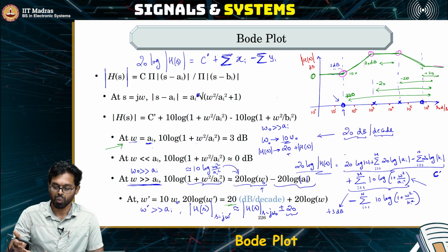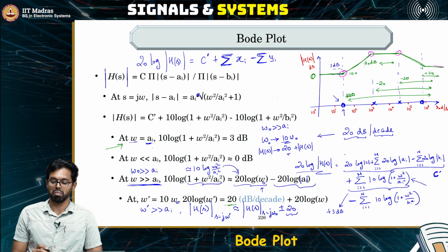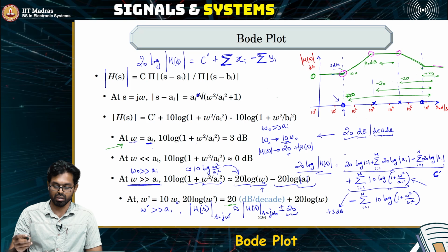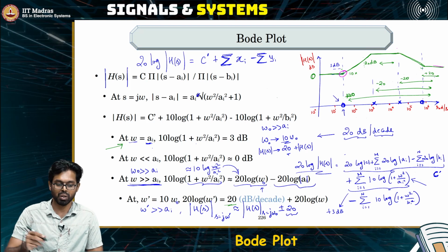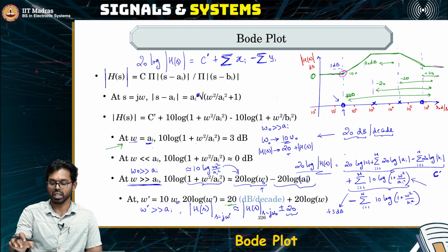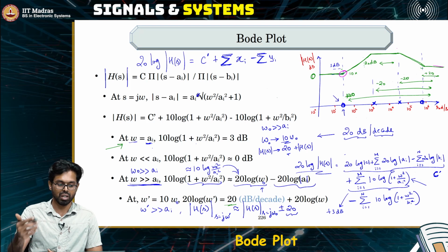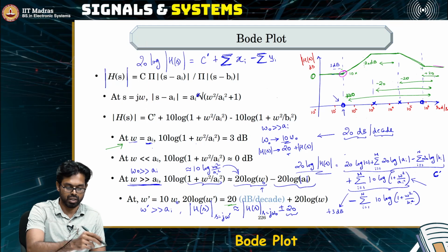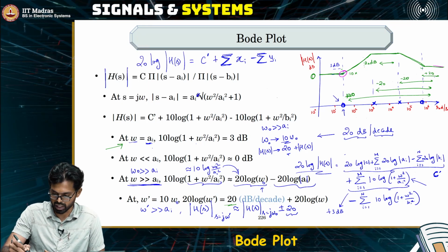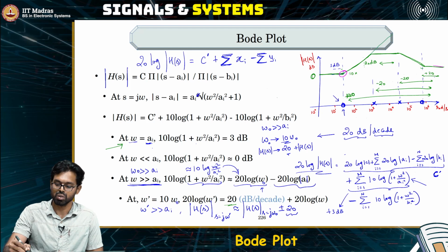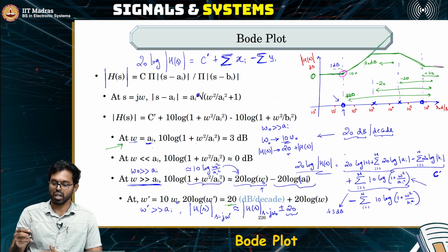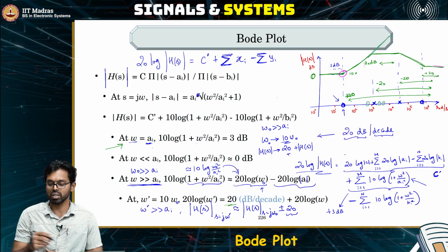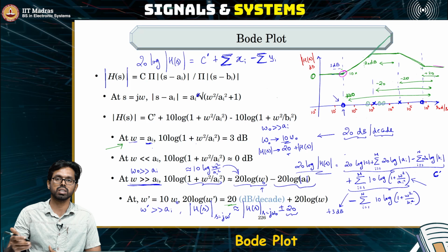Now let us say I want to increase the gain in this band pass region. What should I do? Now this is a design question. So if you want to answer the design question, clearly what it says is I have to increase the gain, which means the slope of this transfer function has to increase. So if the slope has to increase by, let us say, another 20 dB per decade, I want a higher slope here. So what should you do? Which means that you may want to have a 0 somewhere here, right? If you add a 0 somewhere here, then the slope increases even more.